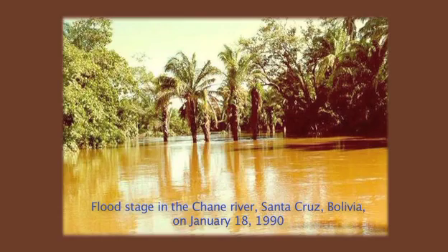Surface runoff occurs when rainfall intensity exceeds the abstractive capability of the catchment. It also occurs when the soil profile is saturated. Large amounts of surface runoff are referred to as floods. Rainfall varies in space and time. For modeling purposes, rainfall can be assumed to vary as follows.